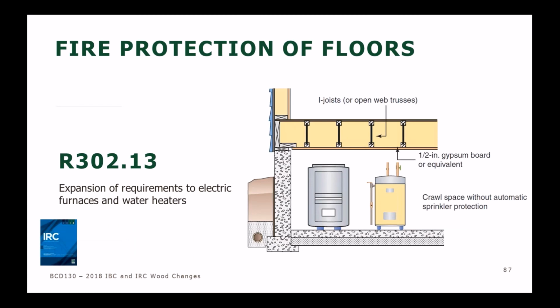So what it is saying is that if you don't have solid sawn lumber joists in a floor and there's a space beneath that floor, so it might be a basement and it might be a crawl space, you're going to protect that space underneath by putting in the 1.5-inch gypsum board. And this isn't a 1-hour rated wall. All you're doing is screwing in the gypsum board. That's it. No taping, no finishing.